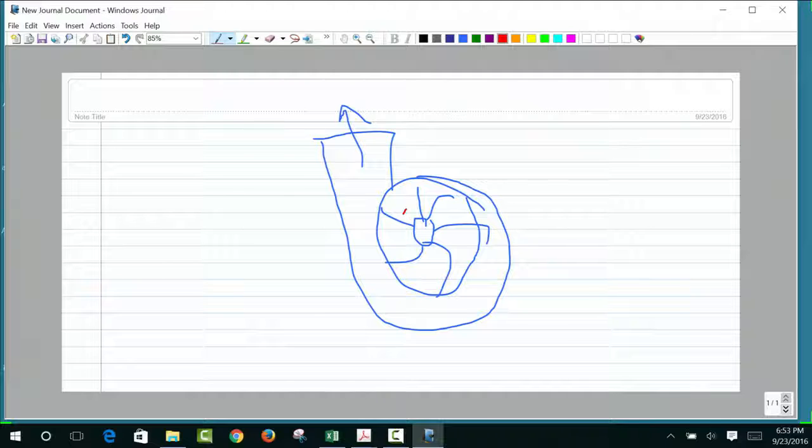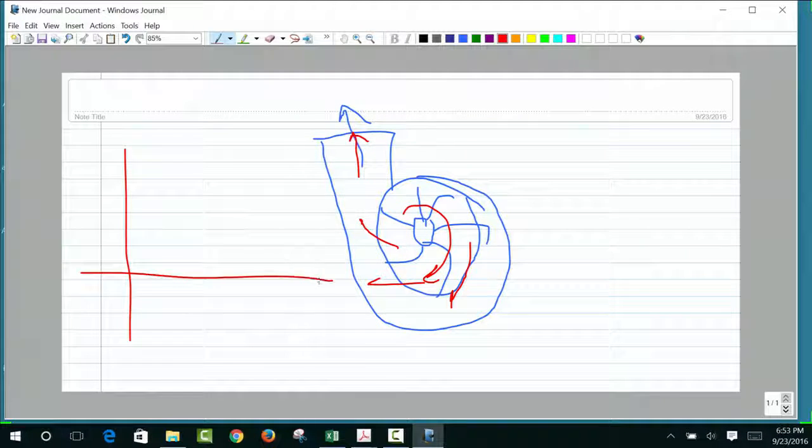As this rotates like this, the fluid gets thrown out, and then eventually goes this way. This has an HQ curve, or delta P versus Q curve. There is a relation between how much delta P you can generate and how much flow rate you can generate.